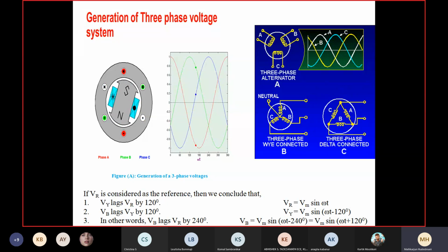In line with that, let us take a view of the three-phase AC generator. We also call it a synchronous generator, having 3 windings and 6 terminals. Those 6 terminals are suitably interconnected to create what I am showing with the cursor, a star. Finally, we find 1, 2, 3 and a common point, only 4. Out of the total 6 possible terminals, only 4 terminals are brought out of the machine. We call this a 3-phase 4-wire system, also known as the star connection system or Y-connected system.